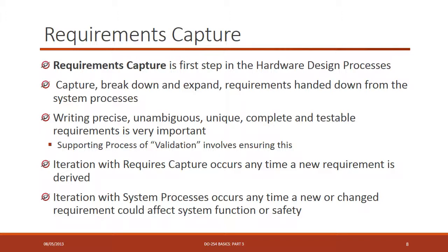But DO-254 programs are requirements-based programs. Requirements are at the very heart of what these flows, these life cycles are all about. So writing precise, unambiguous, unique, complete, and testable requirements is very, very important. And so the process of making sure that happens is called requirements validation.